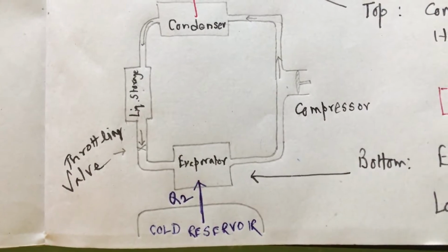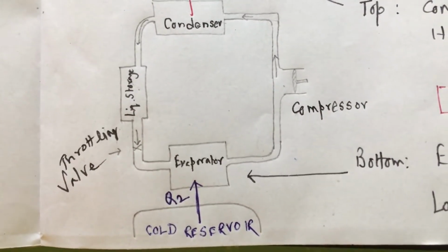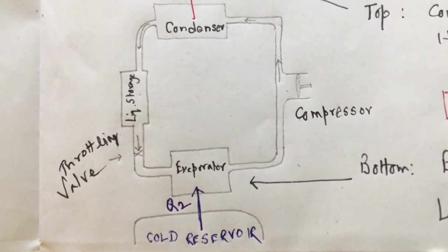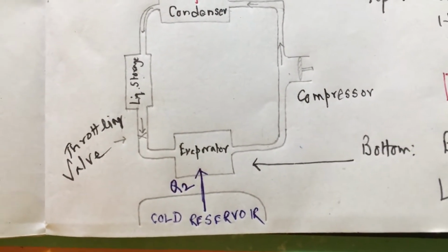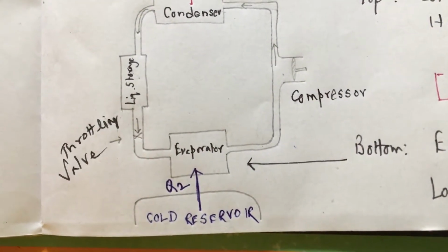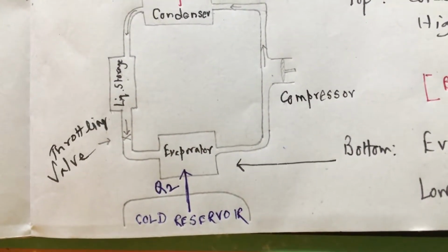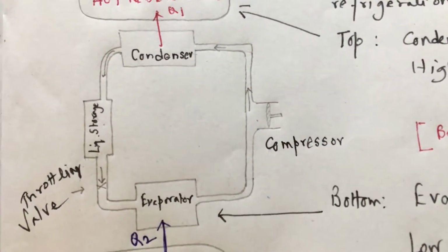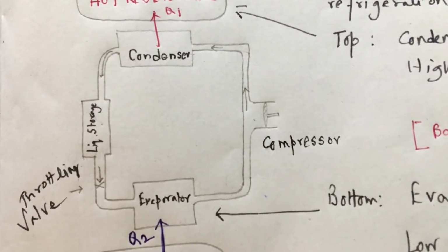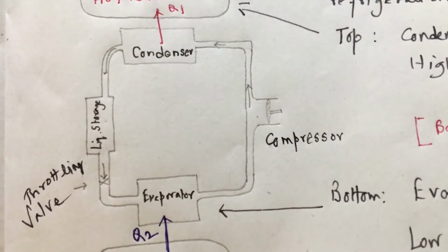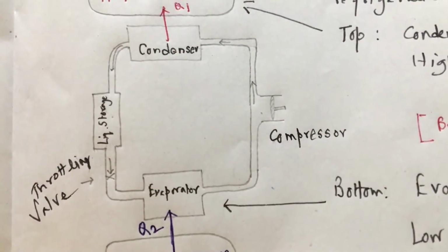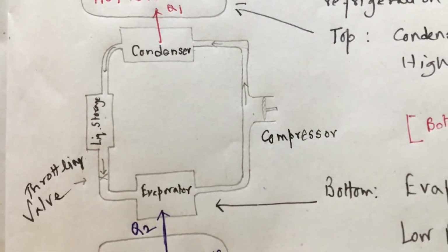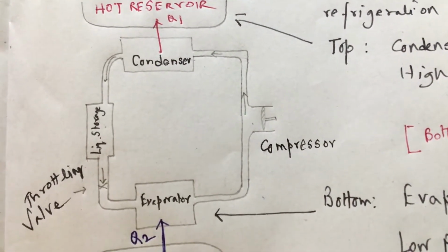So the liquid fluid, which is acting as a working substance, takes in heat, that is, absorbs heat Q2 from the surrounding, cooling them and partially getting vaporized. Again the fluid enters into the compressor to begin another cycle. Now the compressor is actually driven by an electric motor which requires some energy input, and it does some work W on the working substance during each and every cycle.